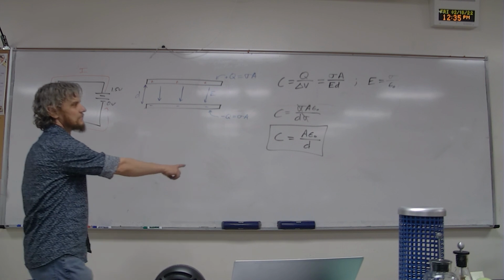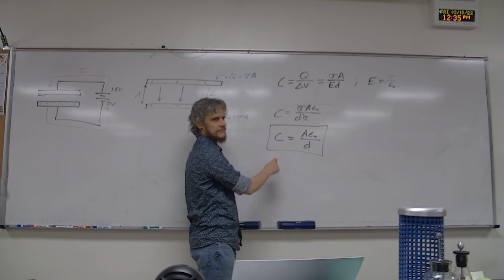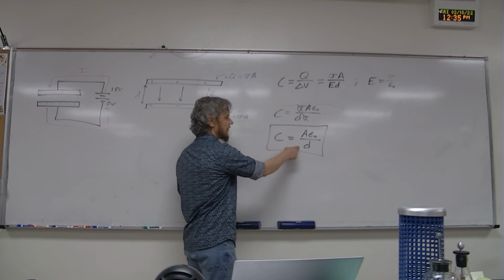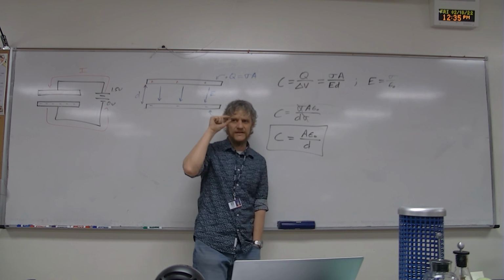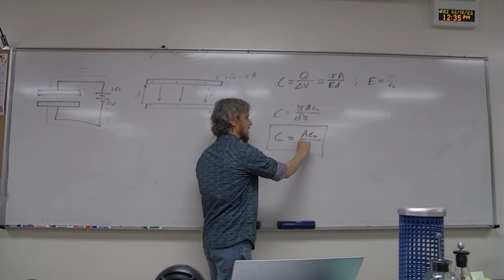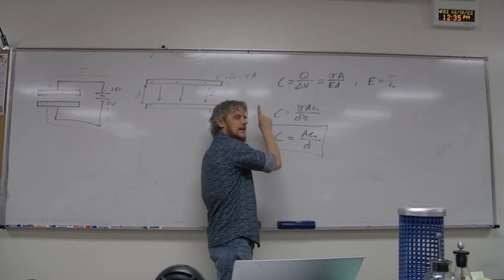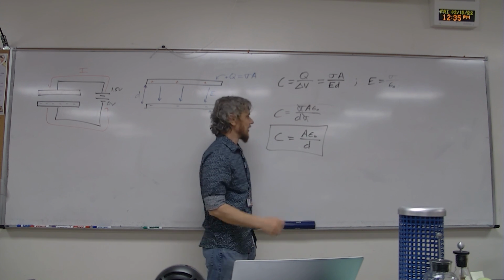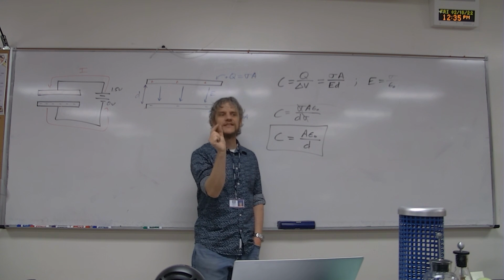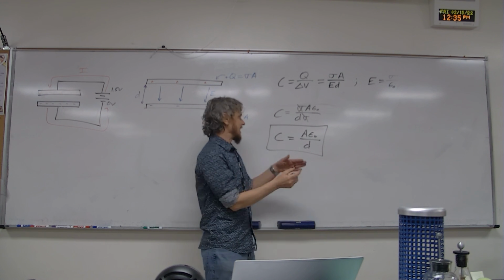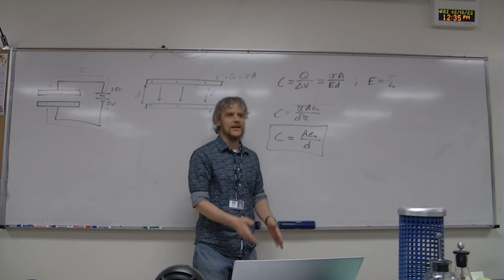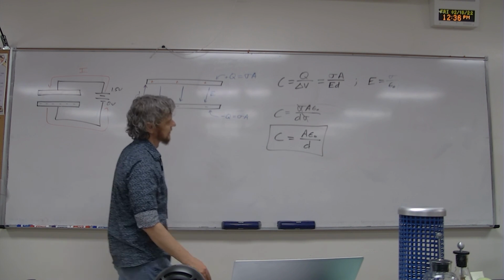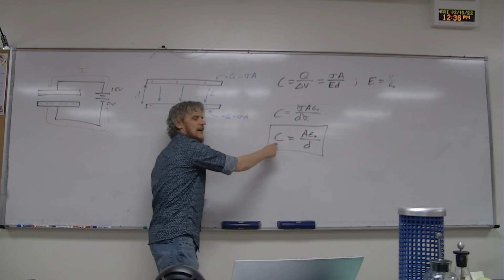But you can get much better capacitors. Yeah, you can make the distance super small. These distances are usually fractions of a millimeter. Very tiny distance. So you make this super tiny and you get the capacitance to go up. Which is why you need a really good insulator between them though, because if you're getting them that close together, the electricity really wants to go from one to another, so you got to prevent that with an insulator. But again, function of the geometry only.